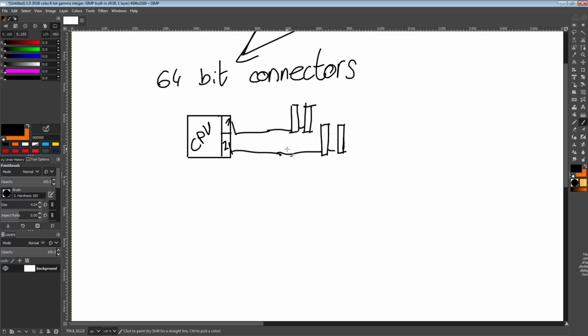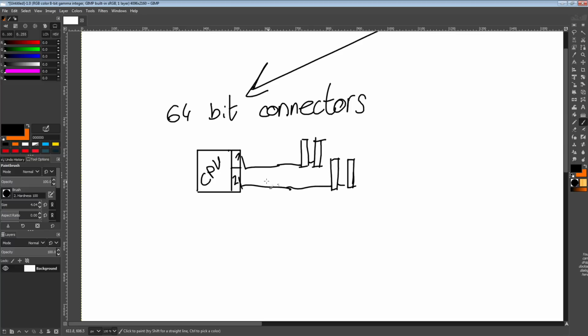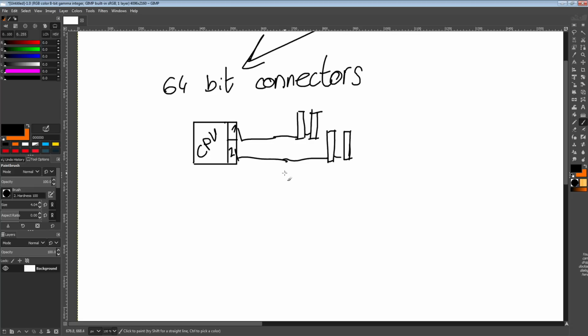Your motherboard, for all intents and purposes, is basically a cable, at least for DDR4. If you go back far enough, you'd actually have logic related to the memory on the motherboard, but these days with DDR4, your motherboard is very much just a cable. Similar to how your HDMI cable connects a GPU to a monitor, your motherboard connects your CPU's memory controller to memory sticks. And you can plug multiple memory sticks into any memory channel, which is why we have two DIMM slots here.